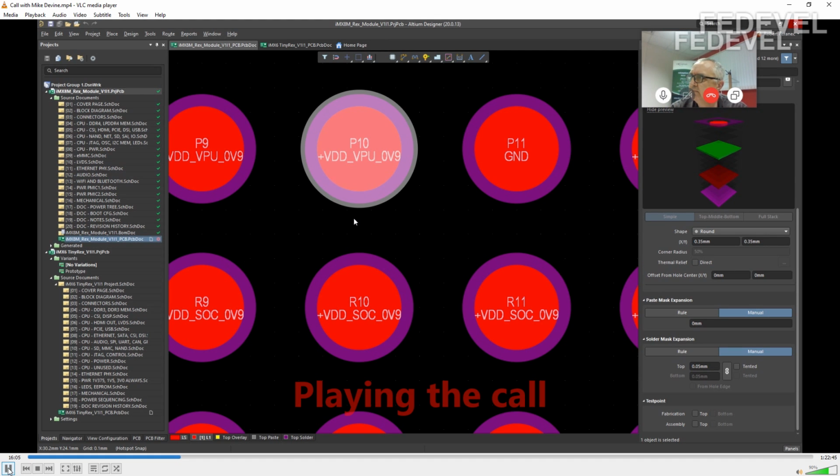Okay. And when we are speaking about the filling, I read you can use epoxy filling or some conductive filling. What is your experience with this? We have two options. Most common is epoxy resin fill, because then that can run through our mass vacuum assisted system. So resin fill, cure, planarize the surface to make sure we remove any surface resin, because that is a big problem if you leave any resin spots on the copper surface, and then plate over.